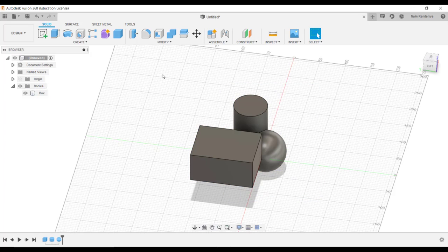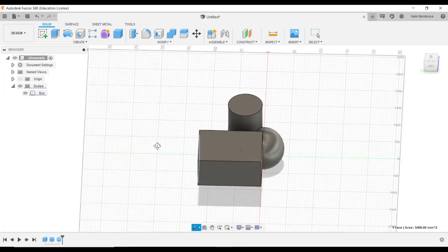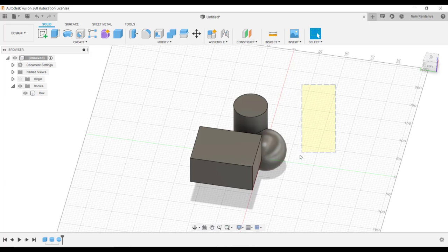Notice when I go with these two motions, they are downward motions. Going left to right, you can see it's a solid line box with a slight orange shaded box. If I try a window select with that sort of selection, notice I only selected that face. But if I go from right to left, I selected everything. Notice that.